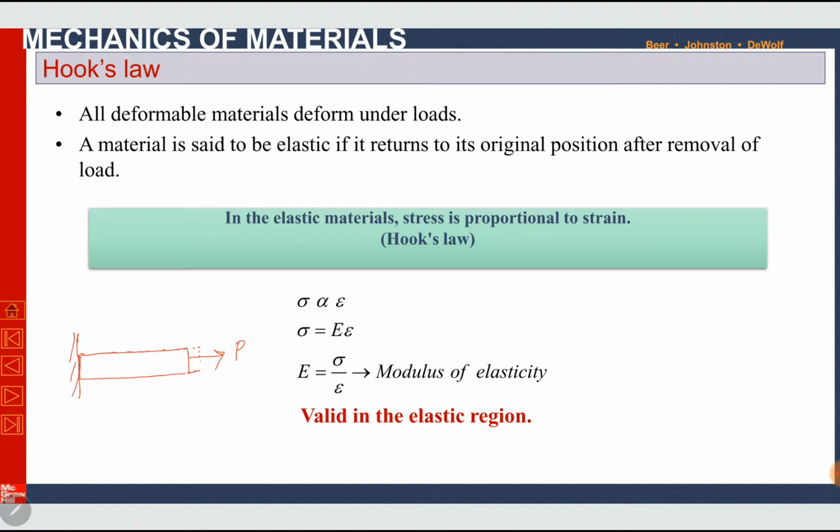and after the removal of the load, if this change in length disappears, the material returns back to its original length. Here it is called an elastic material, loaded up to the elastic range. So in elastic materials, stress is proportional to strain. Even in ductile, non-elastic materials, within the elastic range, stress is proportional to strain. Stress and strain have a linear relationship within the elastic range.